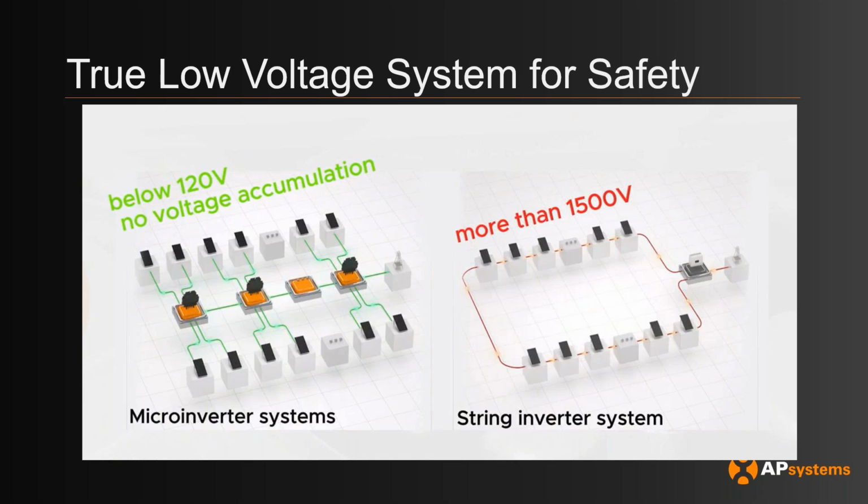Now they're even thinking, and there are conversations about a new UL certification allowing you to not require module level shutdown for panels. One thing I will note is that if there's a scenario where you absolutely cannot tolerate high risk arcing events, then a microinverter is going to be very useful. When you have string systems, you have the possibility of high voltage, and with high voltage comes the risk of arcs.